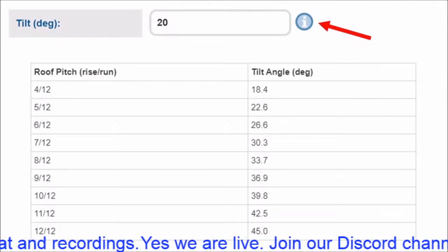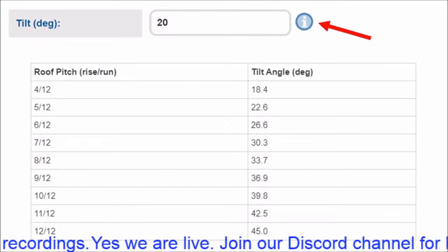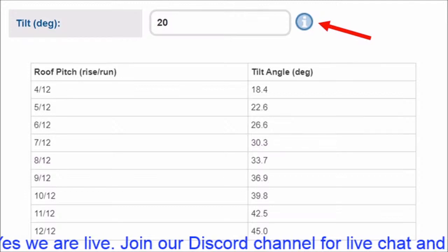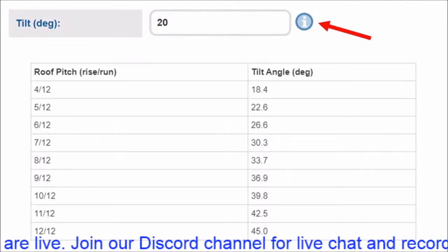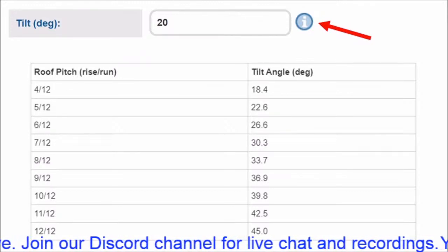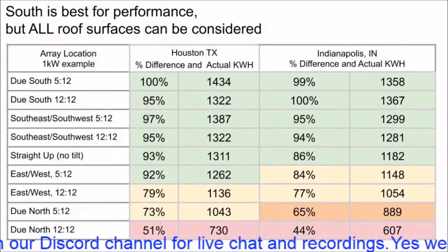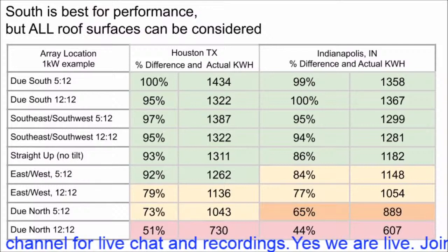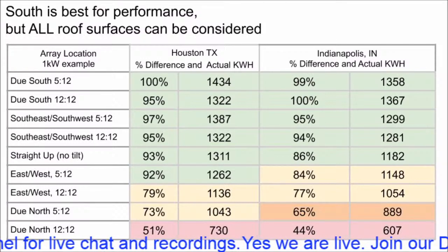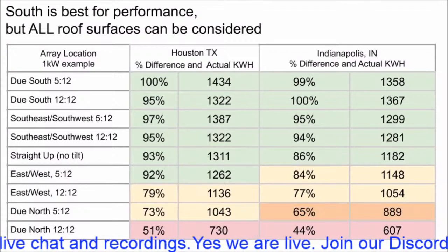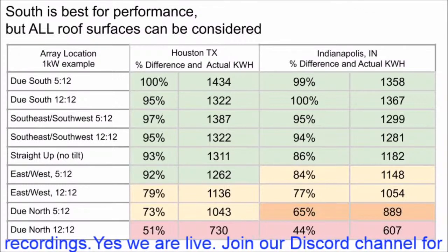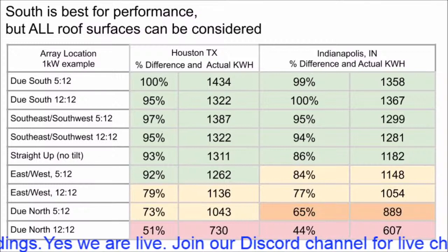For closely examined input data, the roof tilt information button states that a common 5/12 roof tilt is at a 22-degree tilt angle. The solar array is facing 180 degrees azimuth, which is another way to say due south. A 90-degree angle would face due east. A 270-degree azimuth faces due west. All this can be modeled in PV watts.